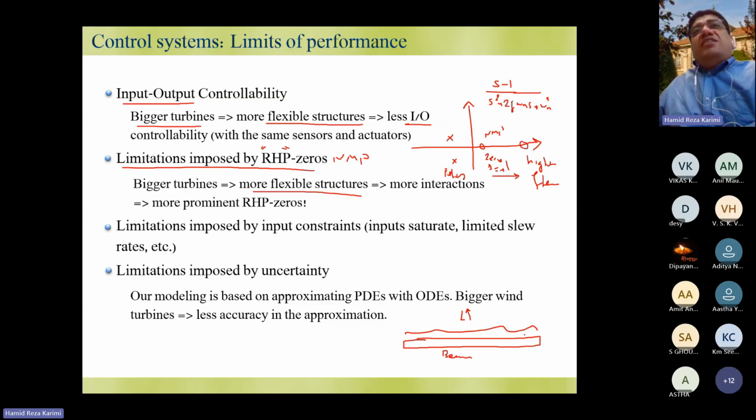Now if you apply the control signal here, u(t), and you want to control this position, it is difficult because at this position you have the NMP. This system has a non-minimum phase zero. In fact, this NMP brings some limitation, and this is a very challenging topic. I'm talking about this s minus 1, for example.